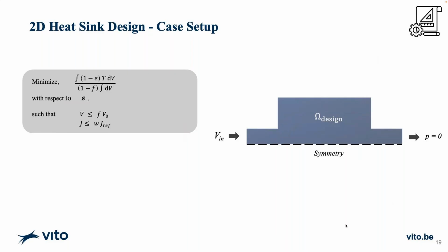Now, in this case, what we're trying to optimize is for maximum heat transfer, because here the objective is that the fluid is able to cool down the electronics or whatever is present underneath as much as possible. So in this case, we are minimizing the solid temperature while constraining again the amount of material it can use.